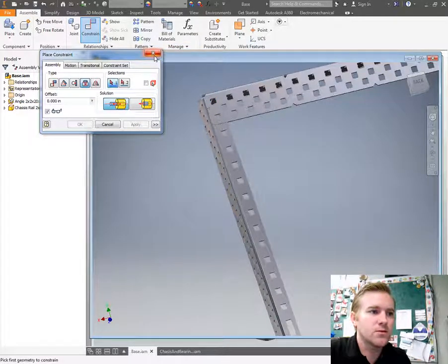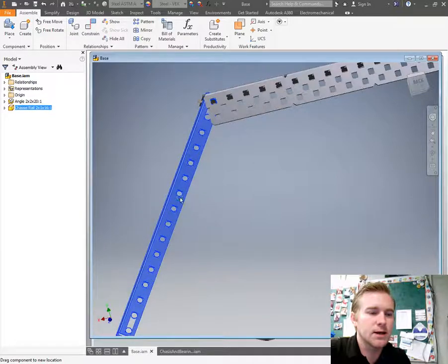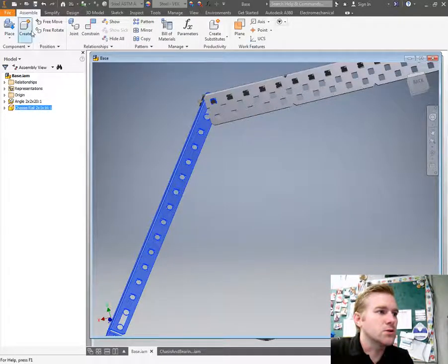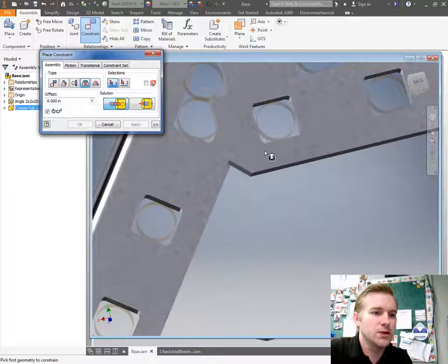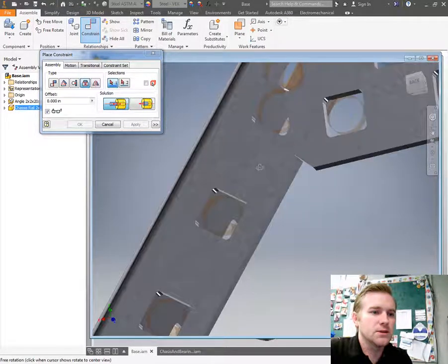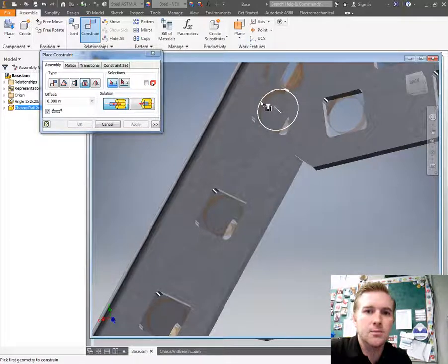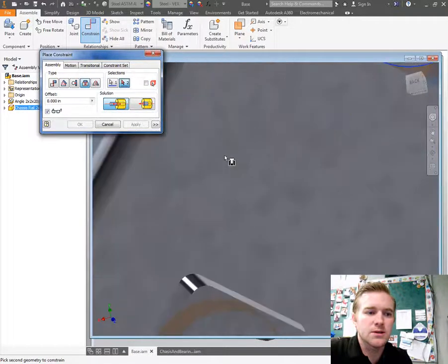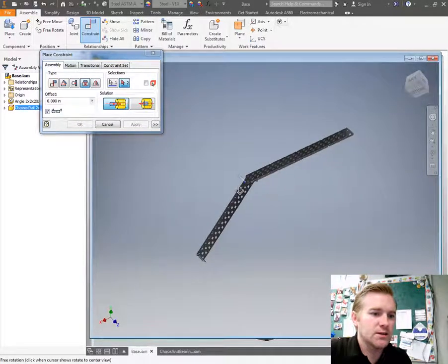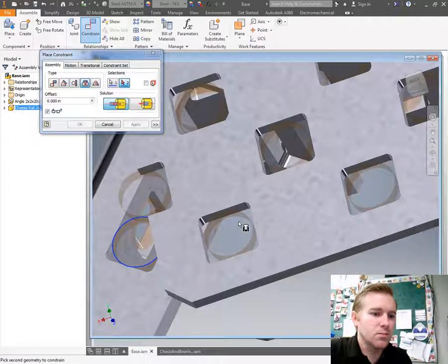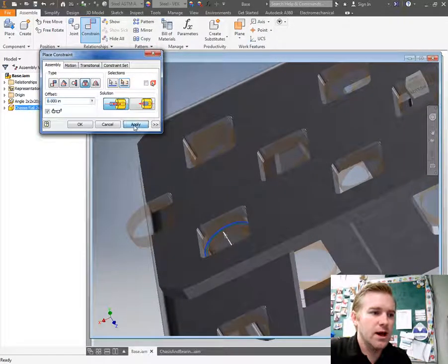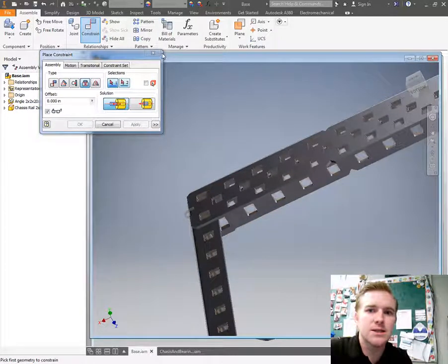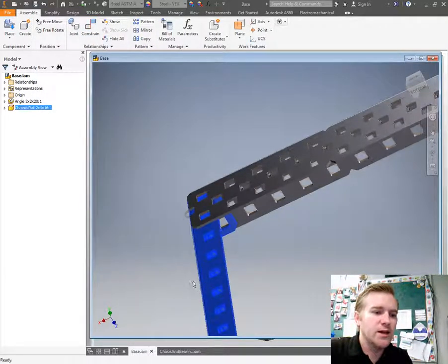And then because this is grounded, if I exit this, I can rotate this out to get a good view of it. So next you want to click on Constraint again. Click on Insert Constraint. Zoom in. Rotate your angle just a little bit. You can click on that top circle right there. This is the top face of my chassis rail, and I'm going to connect it to the bottom face of this, and that'll give us 2 connection points, which will allow that to sit in place and be locked into place. So now if I try to move that, it will not move.